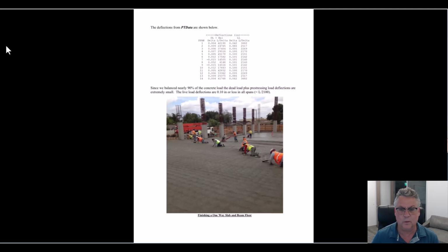Okay, that's it. One-way slabs. Depending on who you are, we'll see how useful that is. You UCLA students, like I said, nothing numeric, but things I like to ask: it's very similar to beam design. One thing you think about is that the 0.004 minimum area of rebar is the same between beams and one-way slabs. That's a very typical question that I like to ask to make sure that you watched this video.